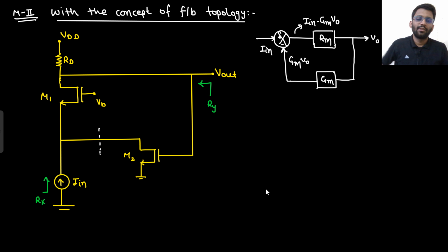Okay. So now if you need open loop here, what does that mean? You need zero current. Zero current should be coming in. This current should be 0. So if you are breaking the loop here, what should you do here? It should be open circuit or short circuit? Tell me. It should be open circuit, because in the feedback path there should be 0 current. If you need 0 current, that means you need to make it open circuit.